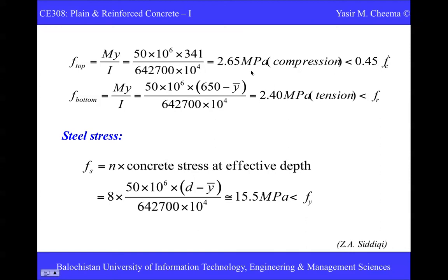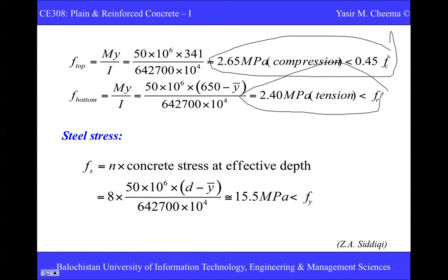You see here that in the previous slide we made a check, so the same is here. Let's say the 0.45 times f'c you use there, that's just an example. Again here is the modulus of rupture check. So don't forget to apply this check. Actually this check helps you to know whether your section is on the safer side. It means if it is less than these values as recommended by the code, you are okay, your section is okay, so no need to worry.